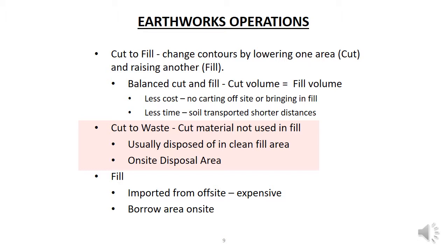The excess or unsuitable material may be carted and disposed of off-site to a clean fill, but this is expensive as you have to pay haulage costs and tip fees. Where possible, a better solution is to have a disposal area on-site which is not supporting the road and where the soil can be laid.